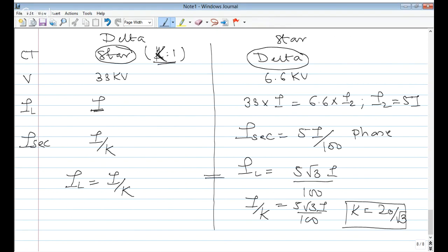Why? Because in case of upper critical frequency, if I assume a symmetric characteristic, upper critical frequency is this much. So this itself will be counted as the bandwidth. So bandwidth is 10 kilohertz. So 20 into 10, it should be 200 kilohertz. Okay, so I think this should be the answer. That is, sorry, 200 megahertz. 20 into 10 simply. So kindly let me know what is the answer given. Based on that, we can discuss more upon it.